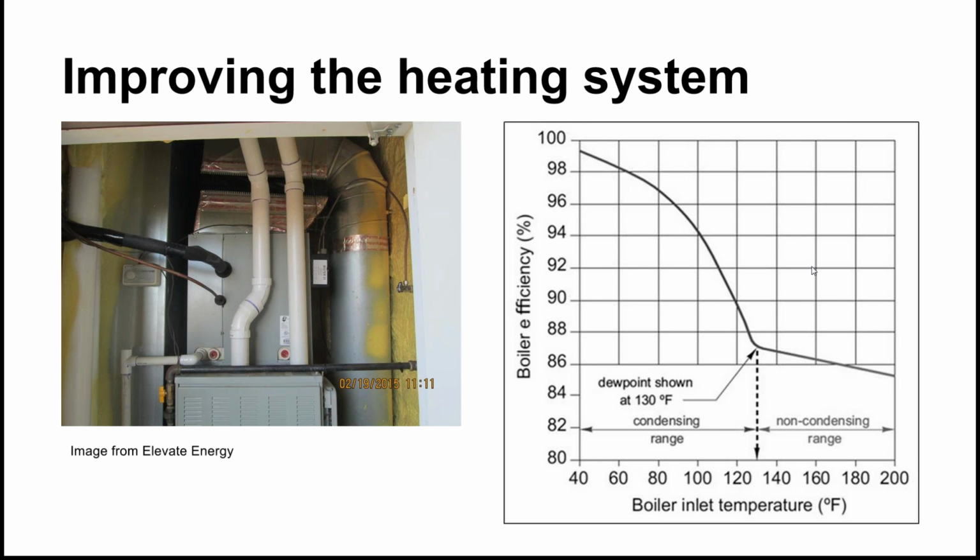So what the condensing boiler does differently is that it recovers the heat of vaporization from the flue gas. So the flue gas preheats the water entering the boiler, and the water vapor in the flue gas is condensed. And you guys are engineers, you know that the latent heat of vaporization, to do a phase change from gas to liquid, there's a lot of heat there. So you're able to heat up the water that's going out to the building to a lot higher temperature. There's a lot more heat exchange going on.